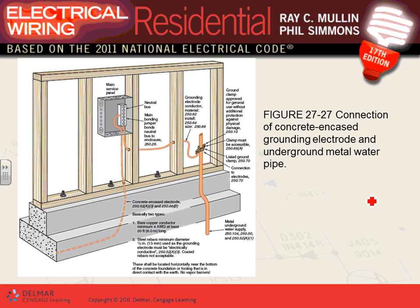Here's a couple of examples, guys. We were talking about the grounding bar. Can you guys see this is the equipment grounding conductor going to the pipe, and another one going to the concrete encased electrode here. So that's how you ground the box. Your neutral, guys, will be in a bar right here. Can you guys see that? This is my neutral. And then you tie the two together. That becomes main bonding, main bonding jumper.